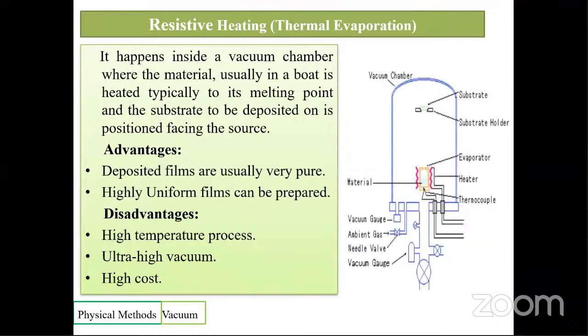Then the resistive heating, basically it is also known as a thermal evaporation type of thing. Here we are using a boat, and it can be done inside a vacuum chamber. The material is melted at a high temperature, which can be heated by flowing a high current inside a vacuum chamber.